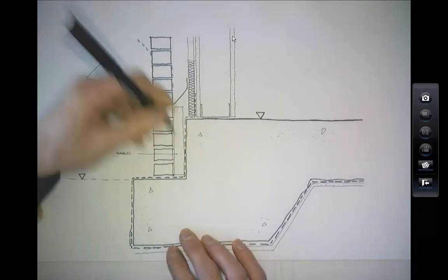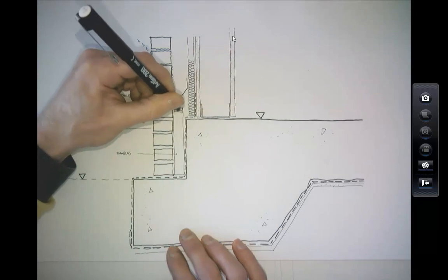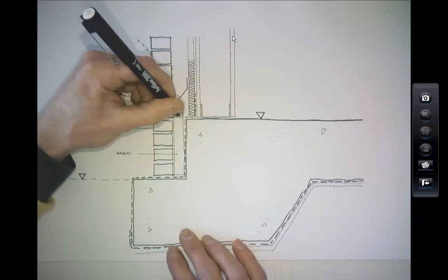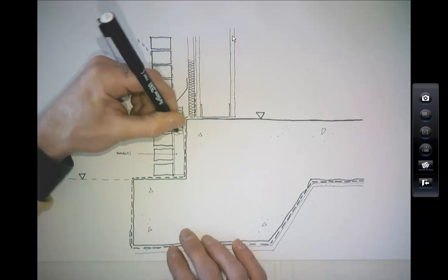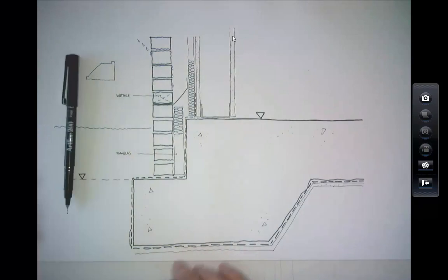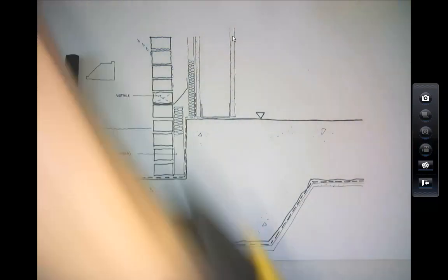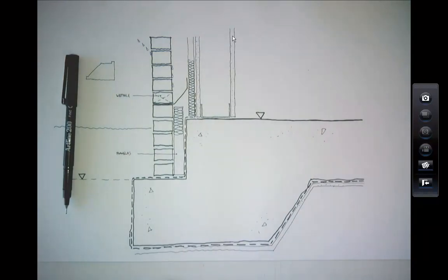Okay. And foam glass is a really great product. It's made from recycled glass. It has very good environmental credentials. It's impervious to water. So even if you stick it in a bucket of water, the water can't get into the air pockets. And it's got very high compressive strength. So you can actually lay bricks on it. Okay, that's foam glass. Pass that around.